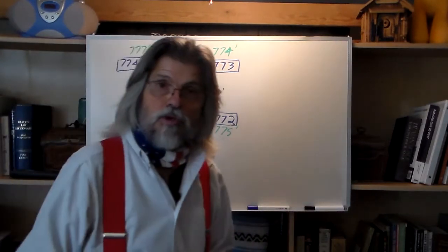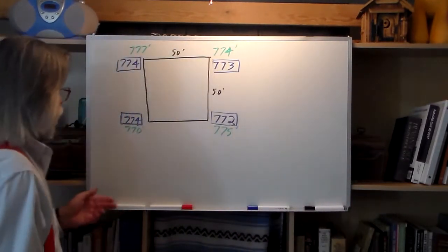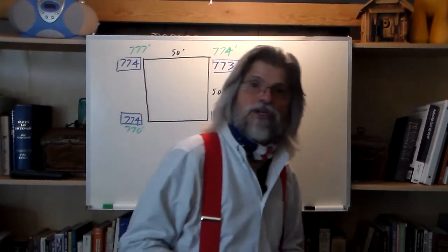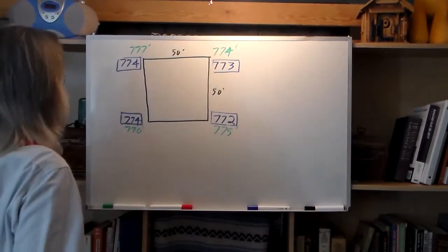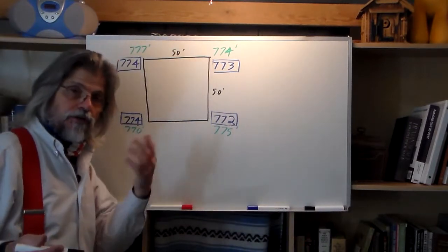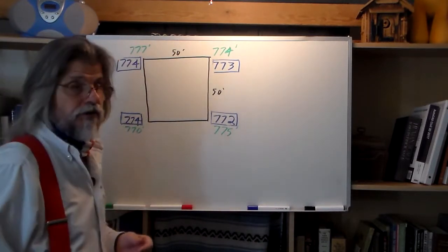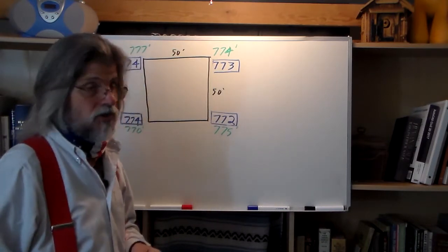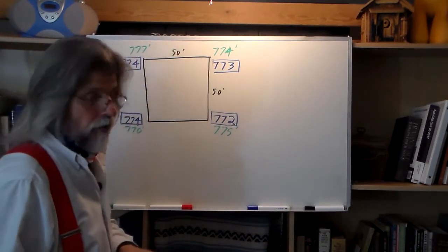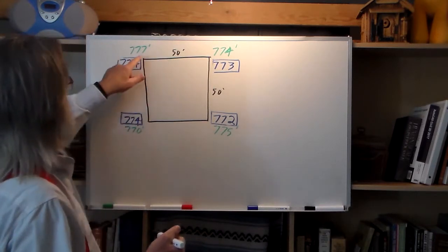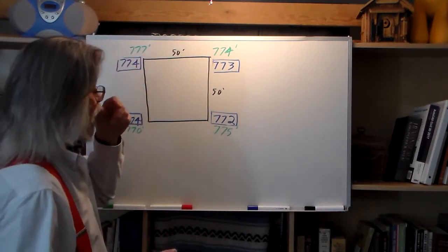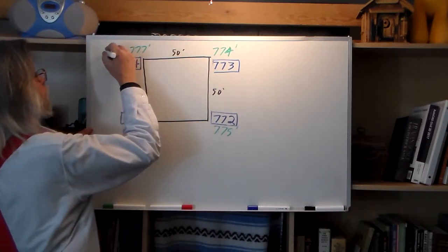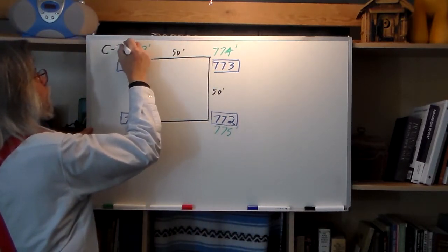So what we're going to do is we're going to do our cuts right now, or fills, as the case may be. The blue numbers are the after, the green numbers are the before. Or if you prefer, in your example, the green numbers are the existing, and the blue numbers in the boxes are the proposed. So here, let's take a quick look. Here we started off at 777. We wound up at 774. That is a cut of 3 feet.